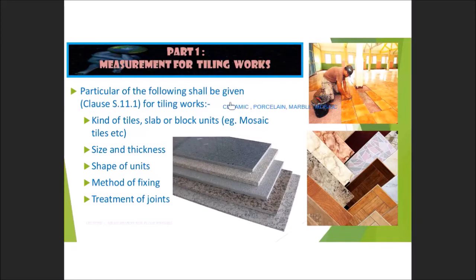And I think you also need to remember, you can refer back to your notes in CT subject. Ceramic tiles we have two. One is glazed, and the other is homogeneous. Homogeneous is normally for the rough surface, and then you also can see non-homogeneous. How would you know? Homogeneous normally has one line. Sometimes you can see two lines very clearly from the side view. So if there are two lines, it is non-homogeneous, because homogeneous means one.